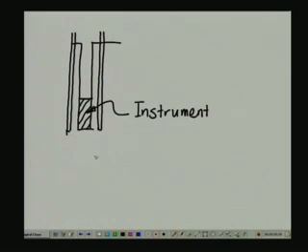and what you can imagine is that as soon as the annular drill bit, which is drilling the larger drill hole around the probe, around the instrument, goes past the instrument, there is a sudden change of deformation recorded within the instrument, and this particular deformation change can be related to the in situ state of stress.